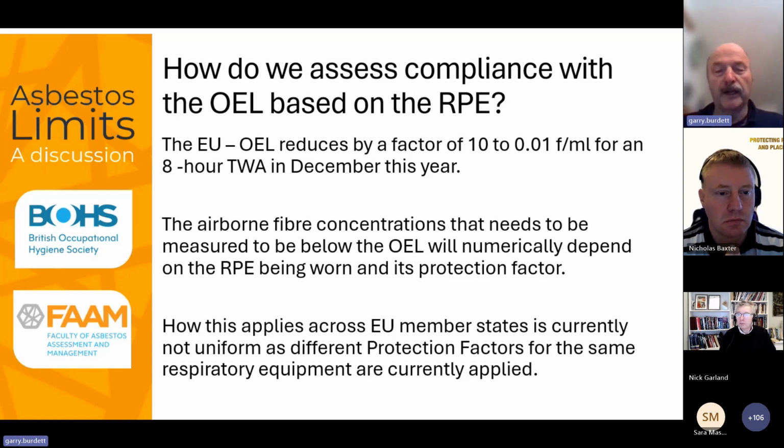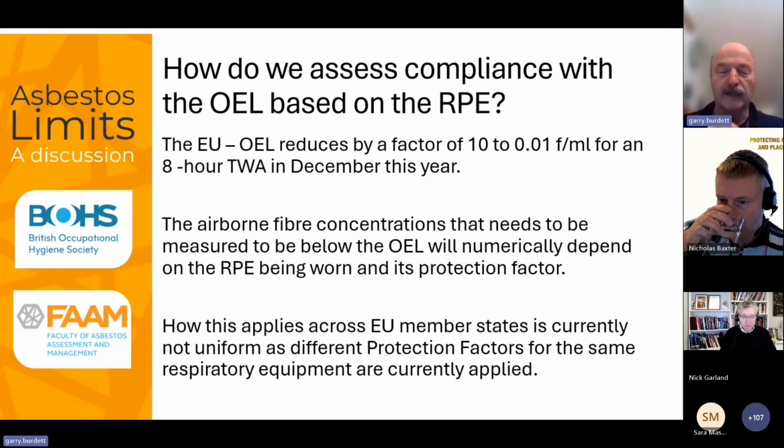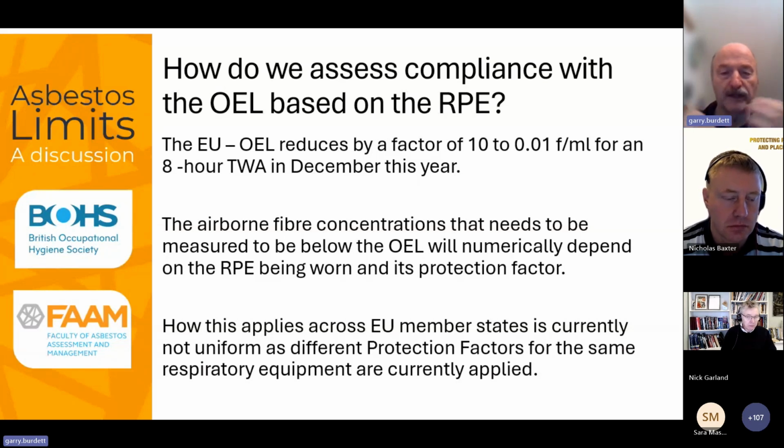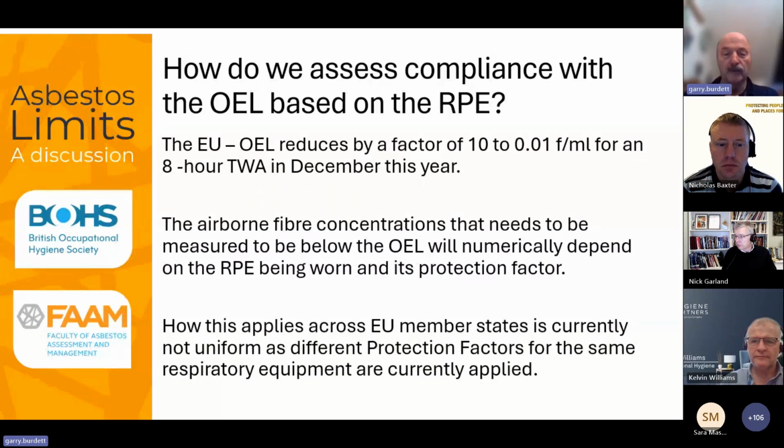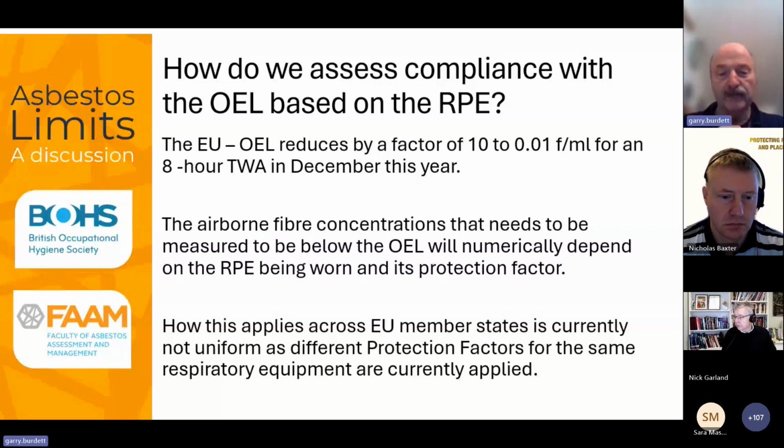You all probably know by now that the reduction in the European OEL at the end of this year by a factor of 10 to 0.01 is quite a sizable issue. And what we're trying to do is get to grips with that in this seminar or webinar series. The important thing is the airborne fibre concentrations that need to be measured so that we are below the OEL will depend on the type and the assigned protection factor of the RPE being worn.